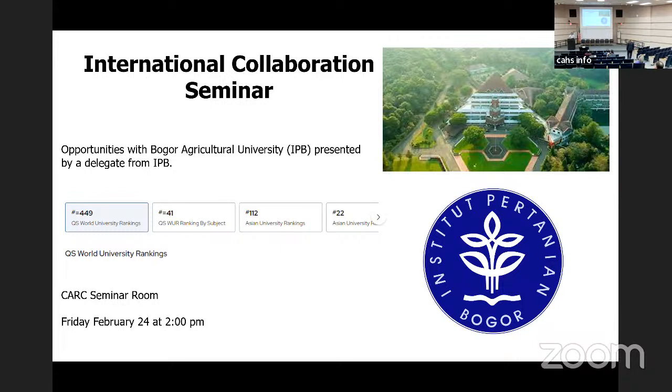We can see that there are different slopes along the way when we drive. So is there a particular optimum slope for different soil categories? Yes, typically TxDOT maintains a 1:3 slope at max. If it is 1:4, then that's good. But because of a lack of proper space, sometimes they have to go with 1:2.25.